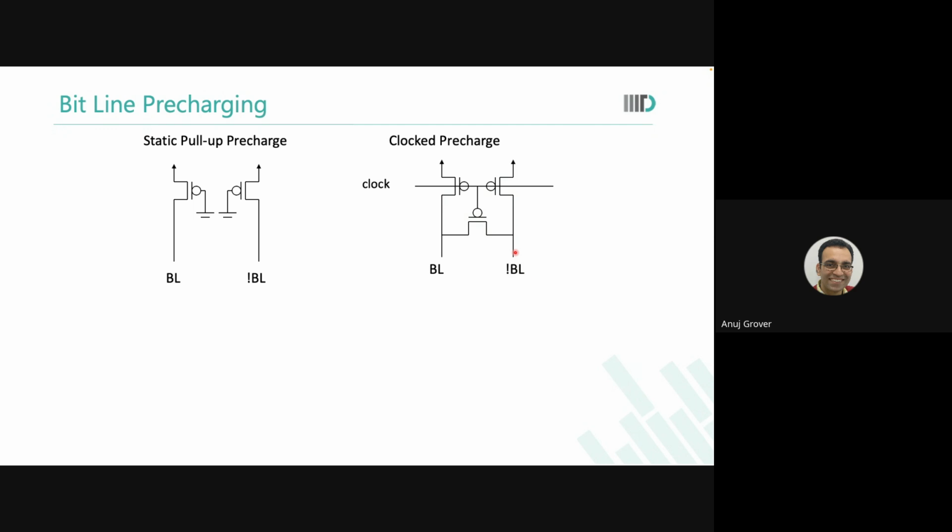Okay? But if you are designing a specific SRAM for a very specific application, where you know that bitline leakage is going to be low when the bitline is at 0, and therefore you say, okay, I will not pre-charge the bitlines. In such a situation, you do pre-charge or equalization at the beginning of the cycle. But then your pre-charge transistors will have to be larger because now they are sized for access time also.